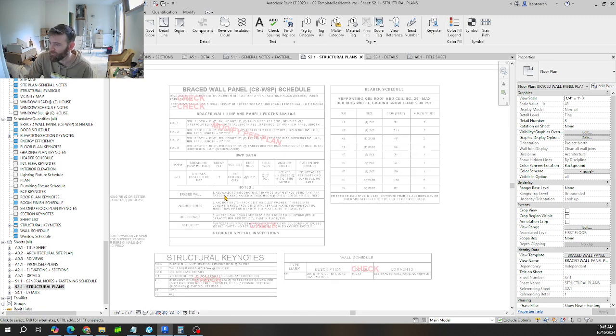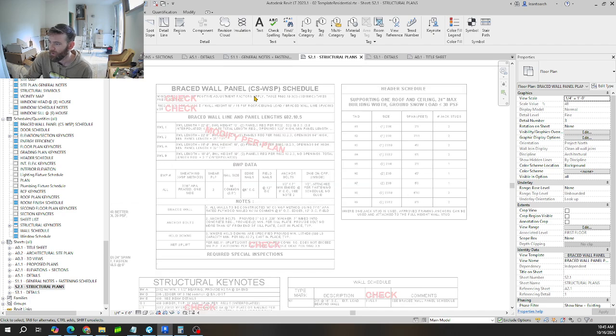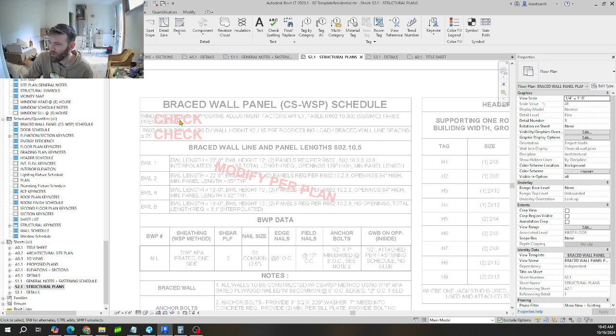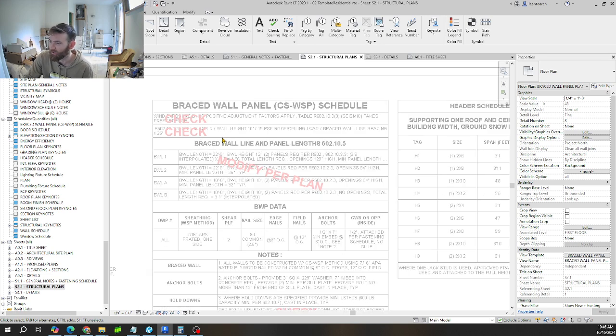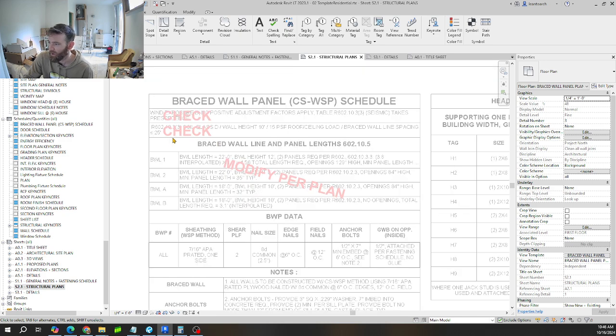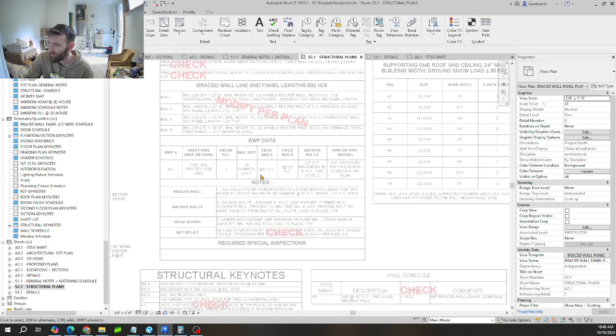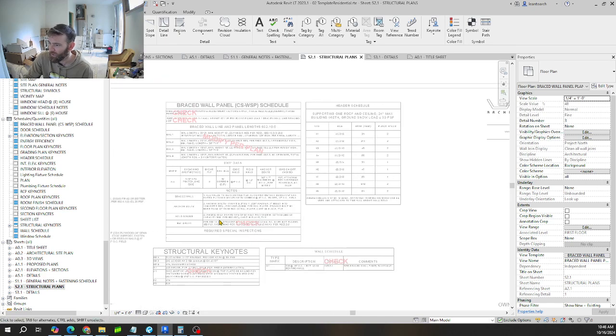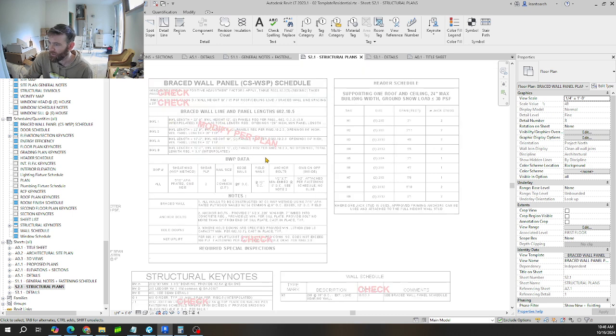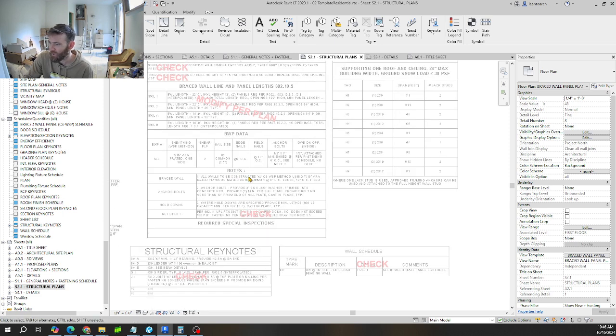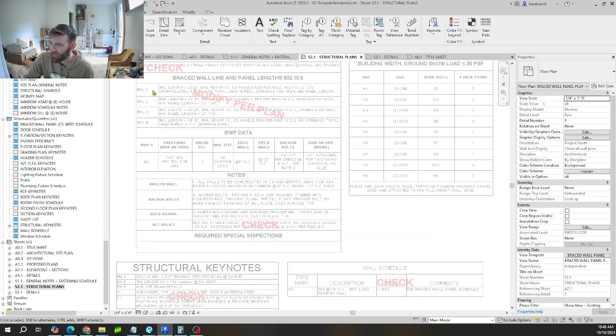residential specialty code, but the structural portion of that code. It's kind of a map logic saying, well, wind doesn't apply because seismic takes precedence. So you use the seismic table. You look at your building height and other things to kind of create this table. So you have to check this table and create a new brace wall panel length portion every time you have a new project here, because these are going to change.